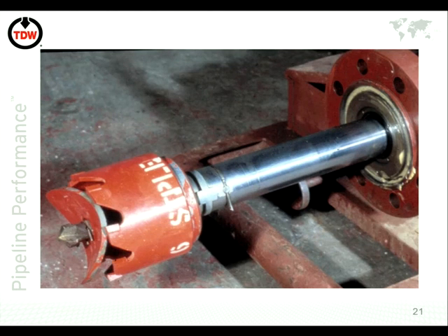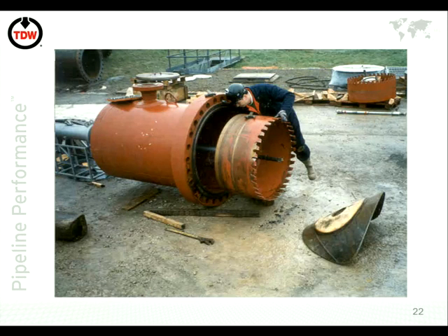Again, this is showing just now the recovery of the coupon. From an integrity point of view, this is an important piece of pipe because this is giving the operator information on the inside of his pipe which he wouldn't necessarily have. He will always have data from ILI runs and things like this, but this is actual visual that he can take. So they do always take this away and carry out investigations on it. And it gives them a little bit of information on the integrity of the line.